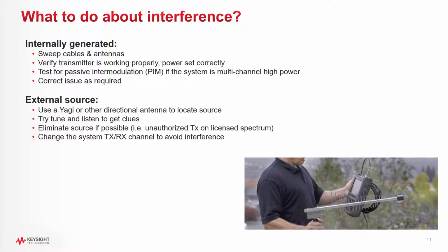So the cellular guys will use these tools, their Yagi antenna, show up at the building, find the jammer, and tell the customer to turn it off, or the customer tells the interferer company to turn off their jammer. Not only is that jammer stopping the cell phone customers within the building from using their phones, but it is going out of the building and causing other people to have problems and disrupting things. It can also be part of what creates that general noise level that causes the whole network to get messed up.